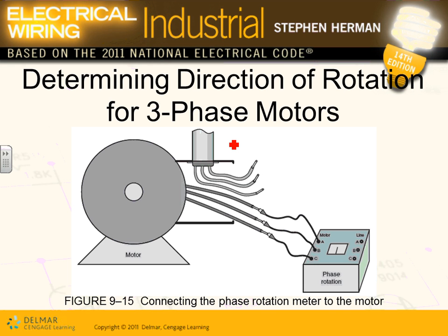Don't you think it's a disaster? Can you guys see it's a disaster? If you flip these wires, you're an engineer in the field, and they're going to hook up this motor. The first thing you should be scared of when they're hooking up these air handling units is, is the rotation right? Are we supposed to rotate clockwise or counterclockwise? How are we going to check that? You know what happens if you have an air handling unit and instead of pulling out the air, you're pulling it in. There are stories of guys getting sucked in and damaged. So I'm letting you know, guys, it's a disaster.